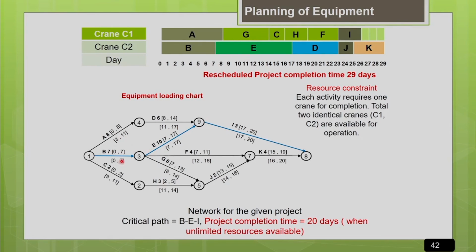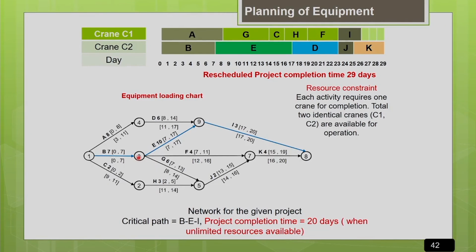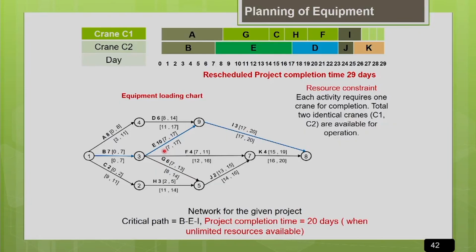The activities which have less float are close to critical. So generally, first we have to allocate the resources to those activities which are critical, that is, whichever have 0 float, that is least float. Allocate the resources to those activities which have least float, then to those which have second least float. So we are allocating resources in the order of criticality of the activities.